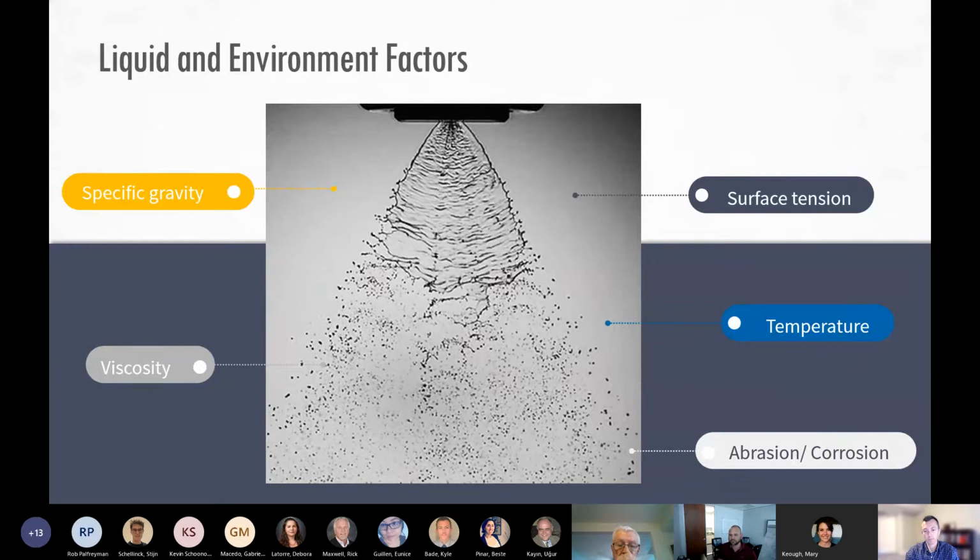Yeah, Kyle, and what you described, and we see this in numerous applications, is that inflection point, right? And that difference between viscosity. Oftentimes, oh, the viscosity makes a big difference, which it does, but also that surface tension, if it decreases as well, that enhances the atomization up to that inflection point. And it's important to understand that distinction.